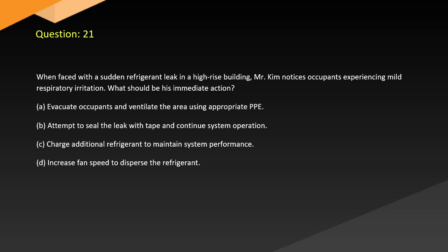Question 21. When faced with a sudden refrigerant leak in a high-rise building, Mr. Kim notices occupants experiencing mild respiratory irritation. What should be his immediate action? A. Evacuate occupants and ventilate the area using appropriate PPE. B. Attempt to seal the leak with tape and continue system operation. C. Charge additional refrigerant to maintain system performance. D. Increase fan speed to disperse the refrigerant.